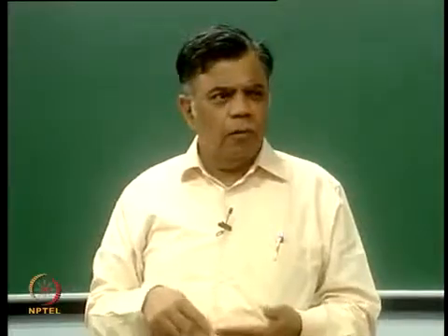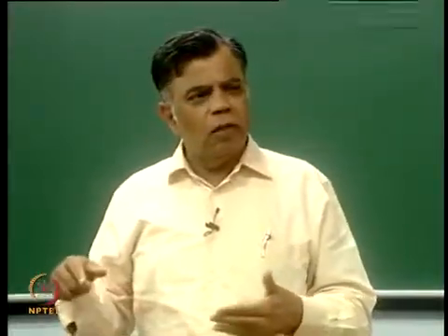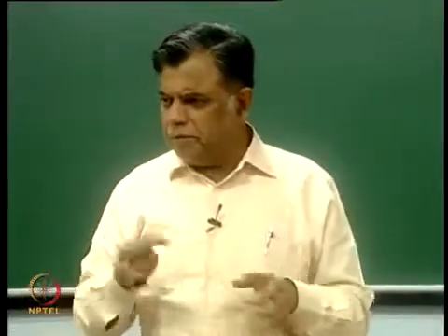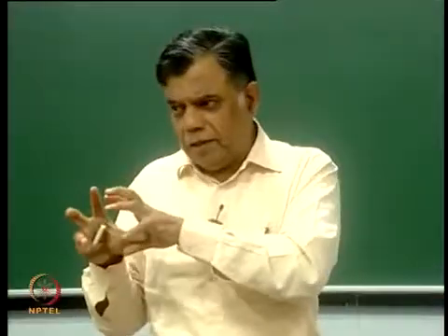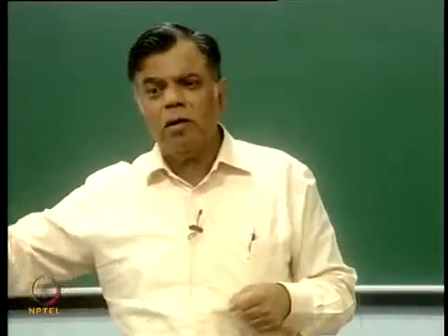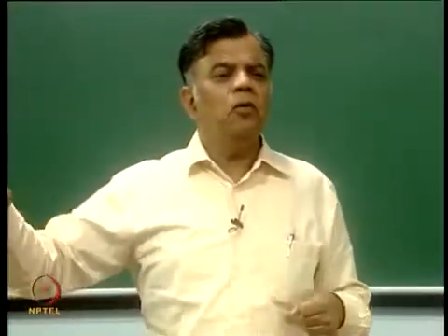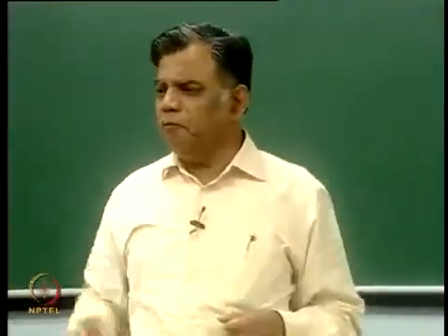Mathematically it is already there in your energy equation, do you remember? u del T by del x plus v del T by del y is equal to alpha del square T by del y square, the simplest of the boundary layer equations, plus q triple prime by rho Cp if you have heat generation, and the last term is what? Mu phi. Phi is the dissipation function.